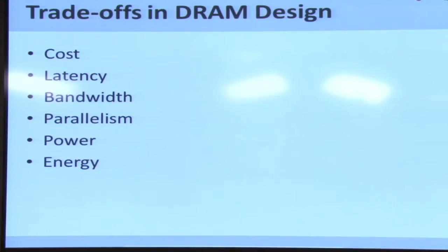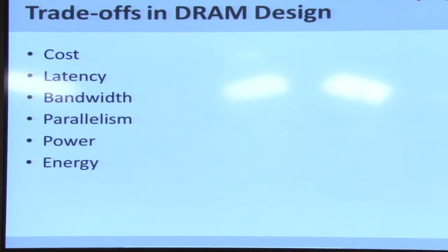If you have fewer capacitors to charge, then your clock cycle could be faster. One second. But here is the thing: when you say lower capacity, there are many ways to achieve lower capacity, right? We have seen a hierarchy in the DRAM chip. There are banks, and subarrays within a bank. So if I build, let's say, a chip with fewer banks, do you think they'll be faster? Probably not much.